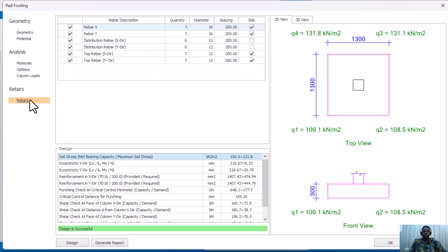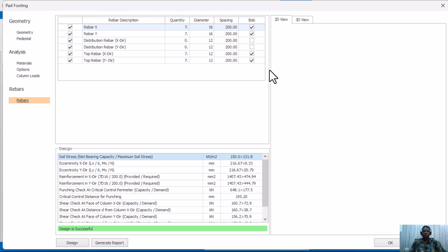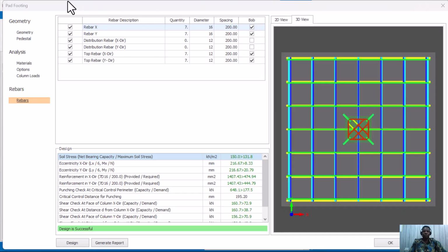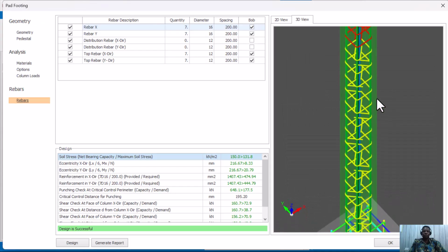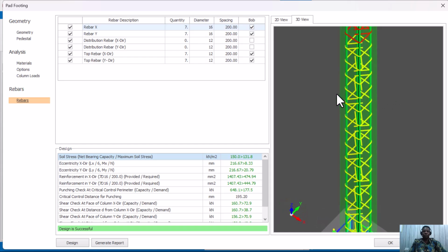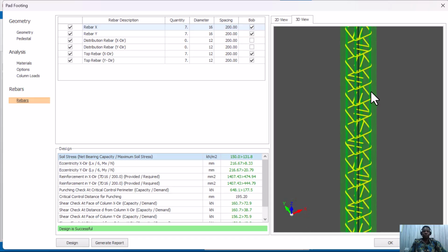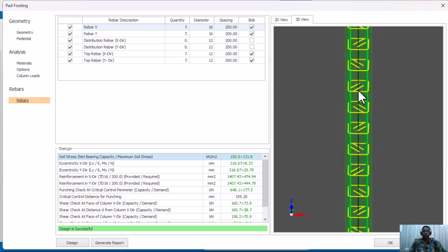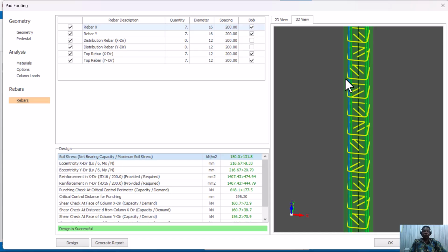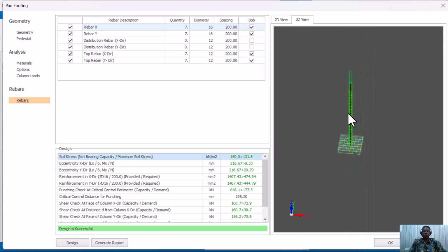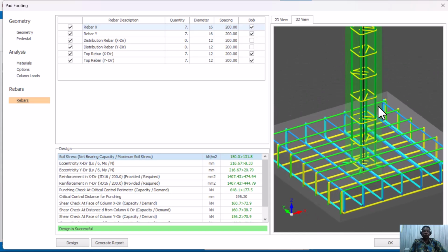So we'll just go straight to the rear bar because that is what concerns what we are designing, okay? So when we come to the rear bar now, if you look at the 3D version of it, you can see even on the 3D, it specifies how your column should be tied, because a lot of mistakes happen on site where you're tying your links and you're not knotting them in different positions. So you have to follow the position provided here, all right?